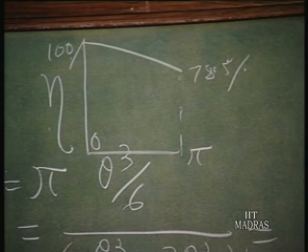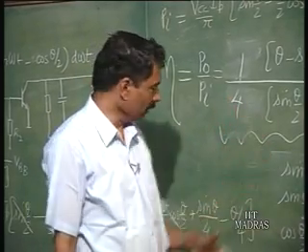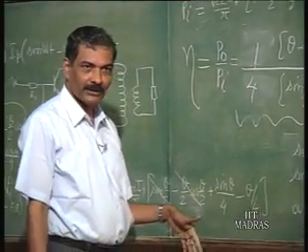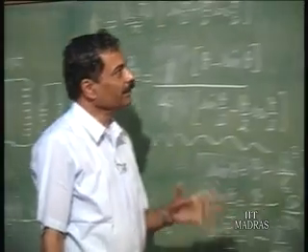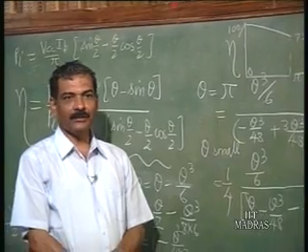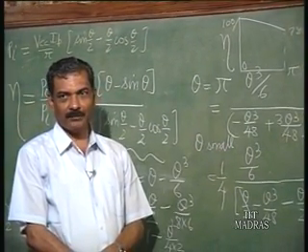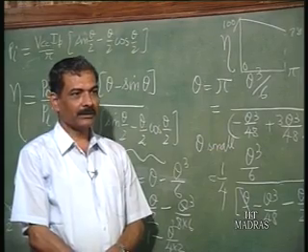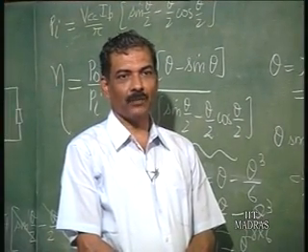Now, this is the maximum ever possible efficiency, under the assumption that we have swung almost up to the minimum, which is 0, etc., and therefore these are all not valid, and therefore efficiency is typically of the order of 70 to 80% for a practical class C power amplifier, which is going to deliver a useful power of about 200 watts.